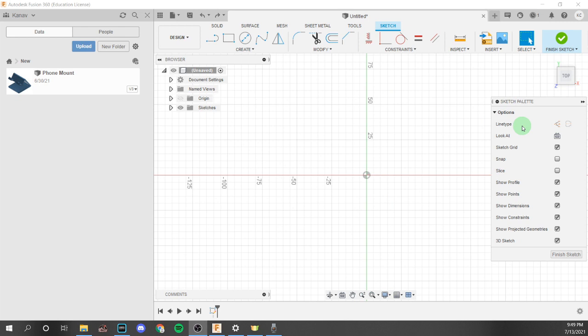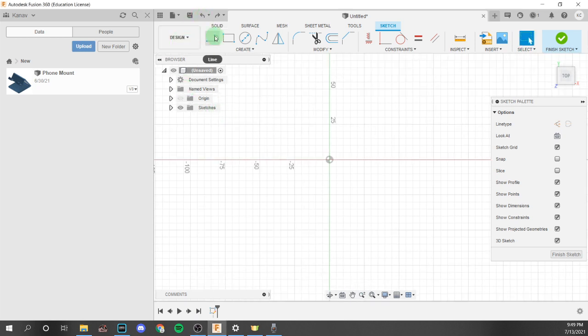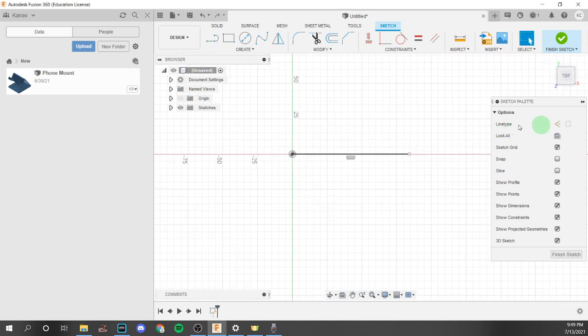Construction is where you would take a line or specific surface, or basically anything in sketches, and you would make it into a reference. Now to give a visual representation, I'll just make a line. I'll make the center point here, just to give it a representation. And once I select the line and I select construction, the line will now turn to a dotted line.